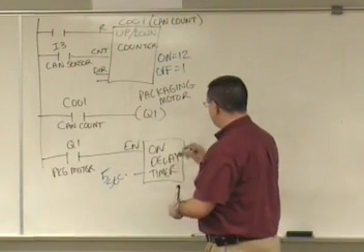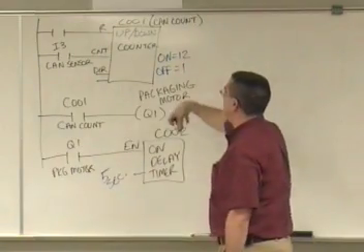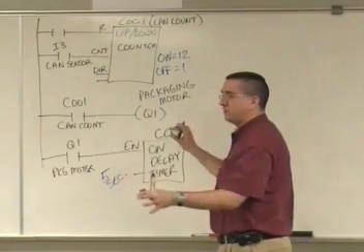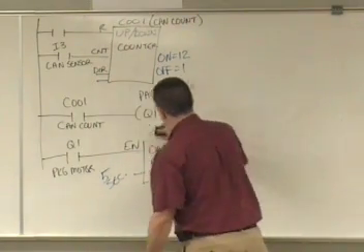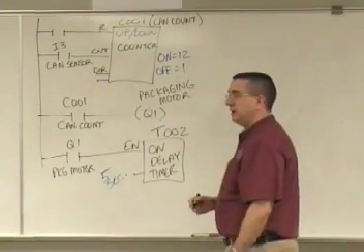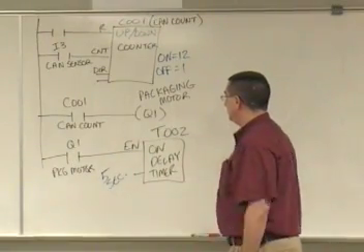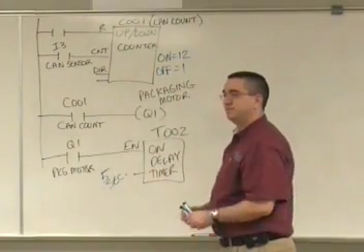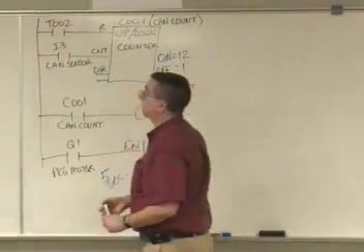And what's the address of this guy? C002, because it's the next available block address. What can I do to make everything work without adding anything else? Is that T002? Oh, yeah, very good. Yeah, it's definitely not C002. It's a timer, okay? It's not a delay timer, it's T002. And what do I do to make the whole system work now and see it loop? You need to label that T002 up top. You got it. And you're done.